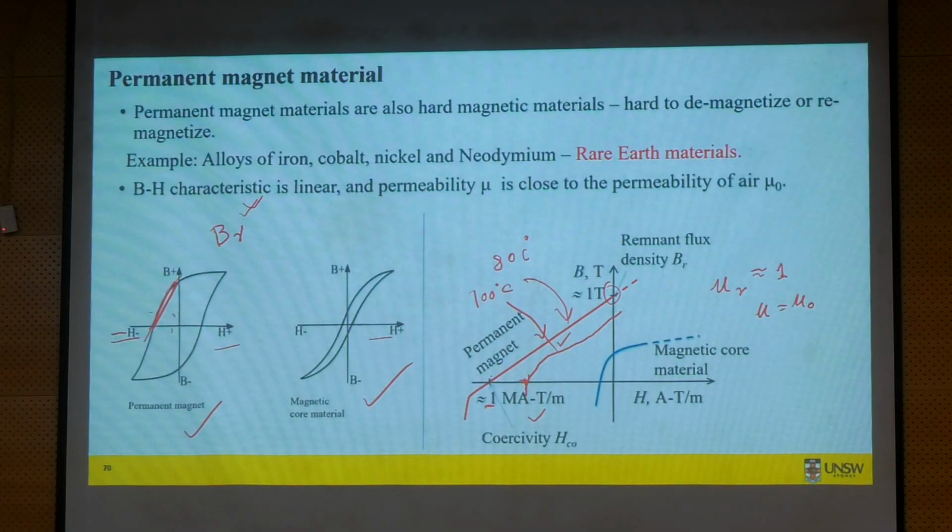So there is research on how to monitor the magnet temperature wirelessly or using some more clever method. That's a big research area, how to monitor magnet temperature. That also relates to the fault-related topic for permanent magnet machines. So for fault monitoring, magnet temperature monitoring is one of the important aspects. Okay.